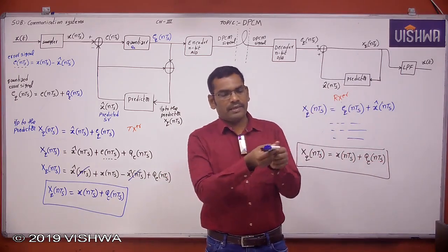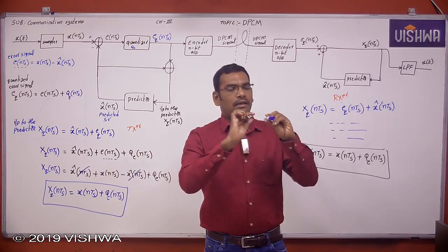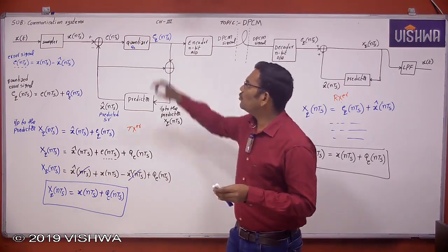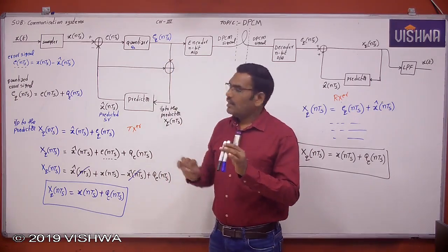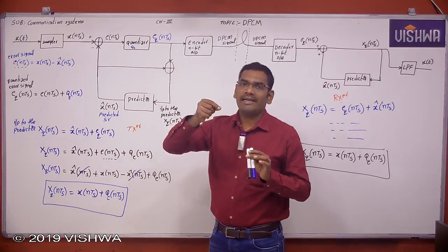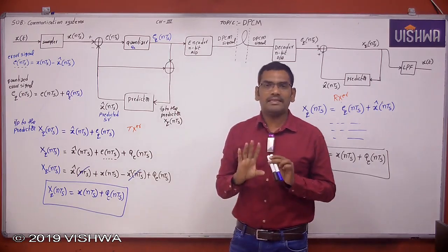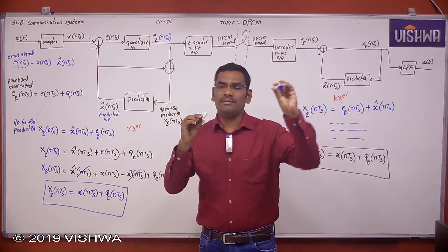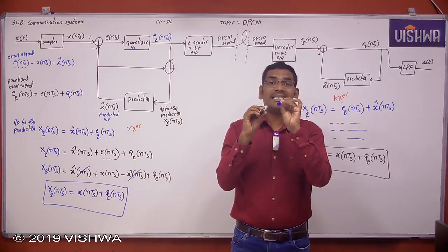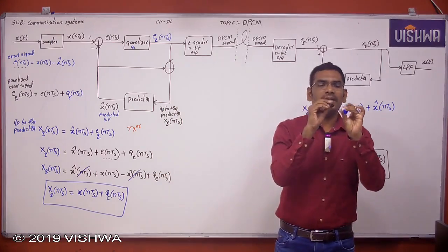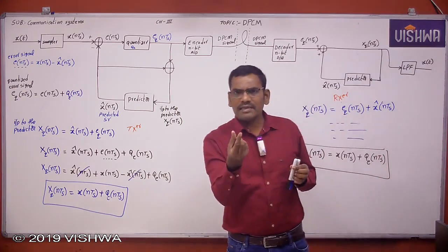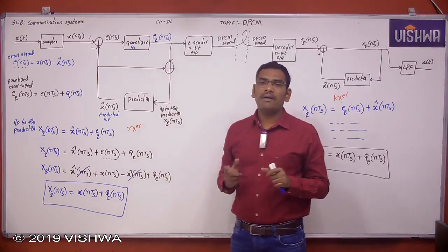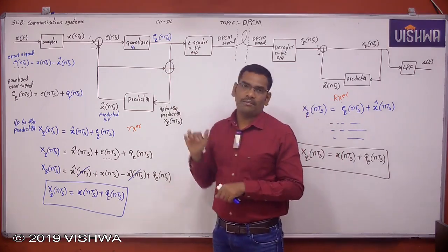This is the present signal. This is the previous signal. Now these two have a difference of Ts seconds. That difference is going for the process of quantization. Now let us take that difference value as 0.8. Now that is rounded off to 1. Understand or not? So this difference is not maximum, not minimum. This is one sample, just a delay of Ts seconds. Now as the successive samples' difference is going for the process of quantization, obviously the error should be as minimum as possible. Understand or not?